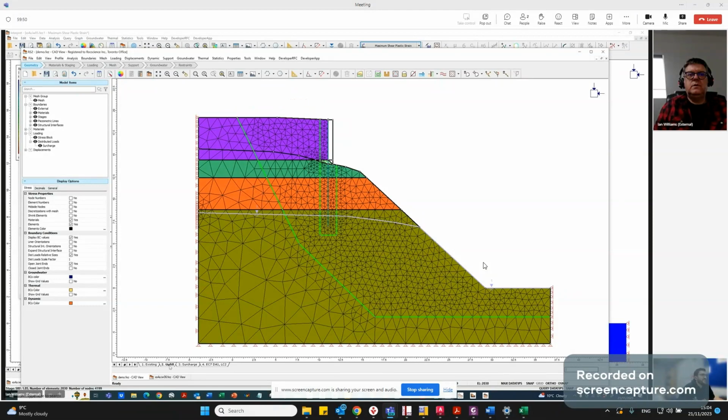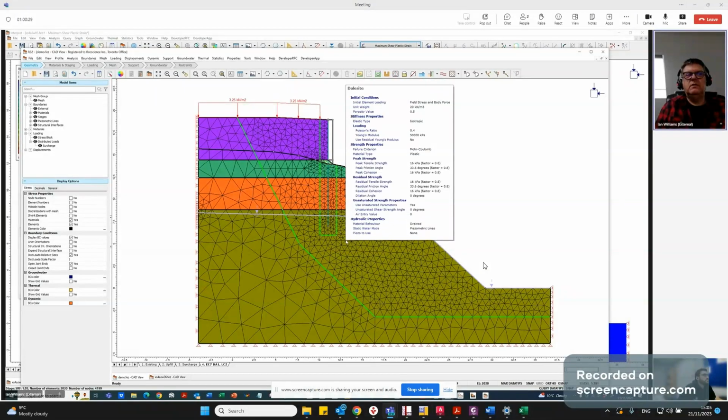Yeah, save it before it goes. So, now if this works, this model should be stable at these loads. Now what you can do, if you were feeling keen, is incrementally, let's say in five stages, increase the load by a factor ranging from 1.0 to 1.4, and incrementally decrease the shear strengths in the soil.